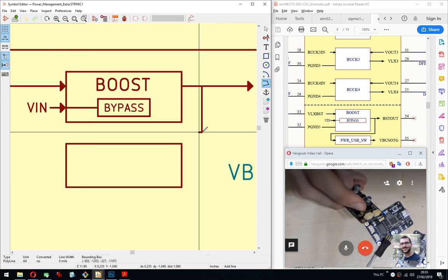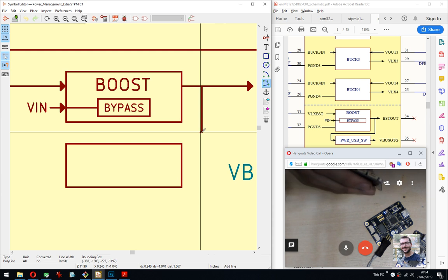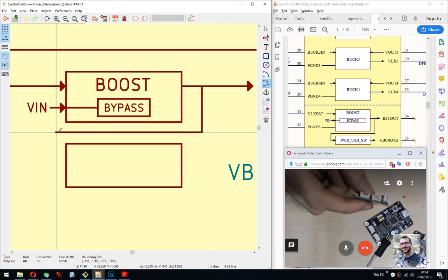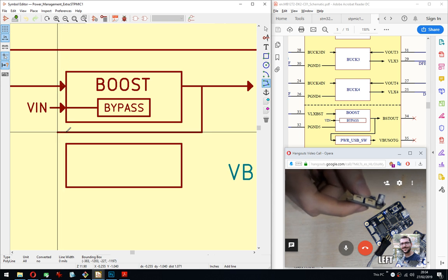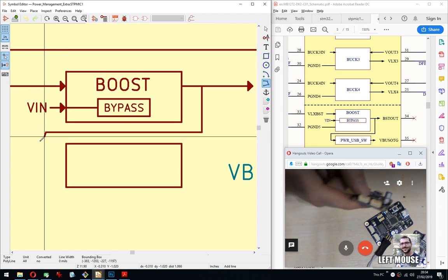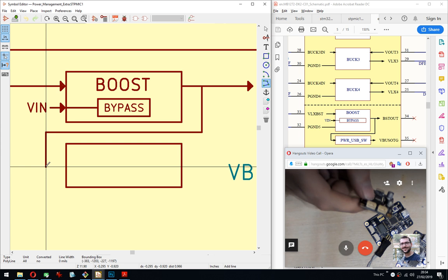The other decision that I made, that a lot of people don't understand or at least ask why, is that I used JST GH plugs. Those are tiny board-to-board connectors, and they're standardized in one CAN specification, namely the UAVCAN specification. So if you want to plug into drones and small flight controllers, you can just do that.